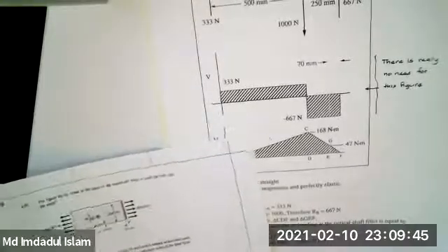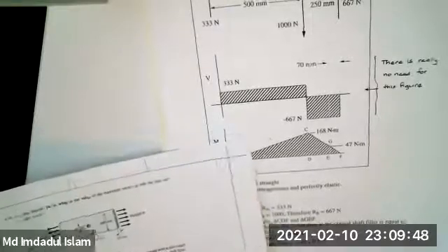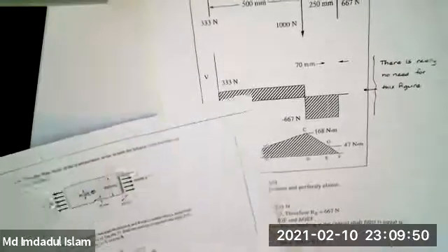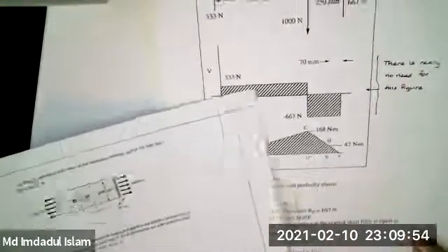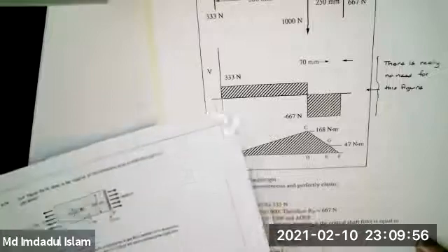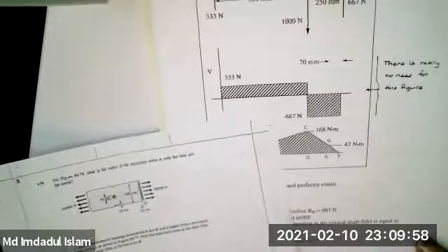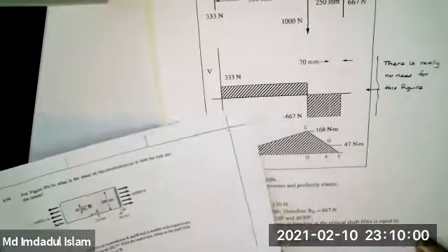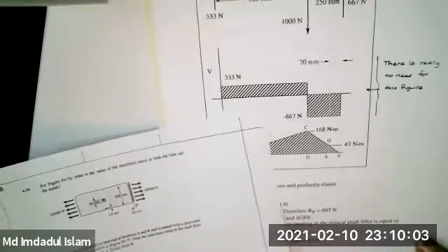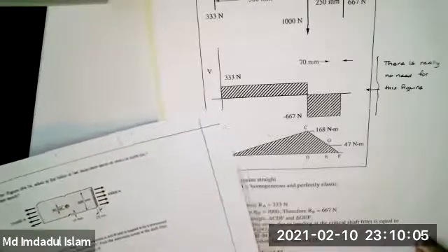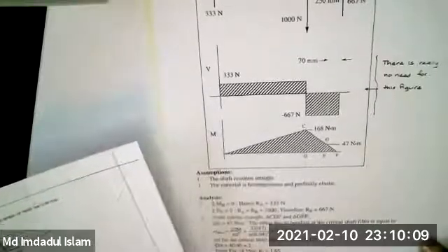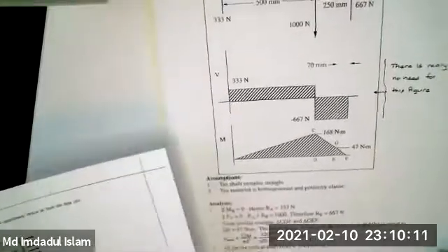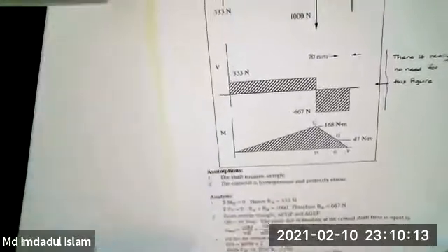But I don't think you're going to have time to do that sort of thing in a test. And most mechanical engineers don't bother with this. Civil engineers tend to worry about shear forces much more. Very, very occasionally in stubby beams, the shear force produces a significant shear stress. It is really rare. Okay. So otherwise the solution is just fine.